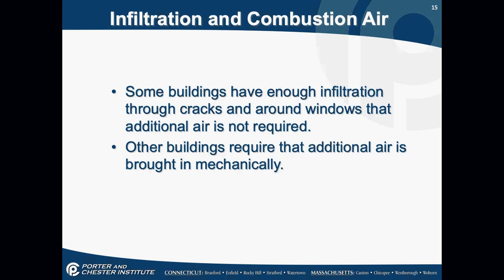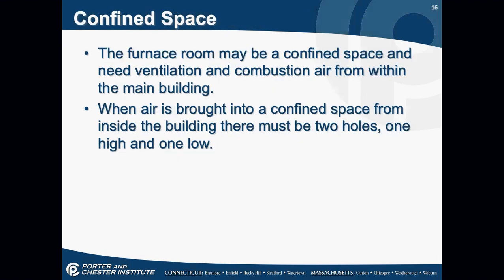An oil burner can actually put a house into a vacuum within 10 minutes of operation. It gobbles in huge amounts of air. The furnace room may be a confined space and need ventilation, and combustion air from within the main building. When air is brought into a confined space from inside a building, there has to be two holes that air comes through, one high and one low.